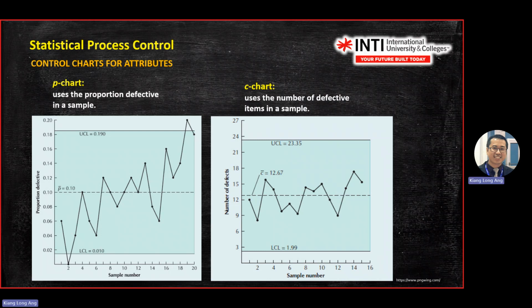After you find the mean, upper limit, lower limit. LCL is the lower control limit. UCL is the upper control limit. There's a formula for LCL and UCL. The formula will be A plus minus Z sigma. It always looks like that, but it depends on what graph you want to plot: A plus minus Z times sigma. So it depends on the question. The Z is the one that you'll see in the question. If they say the sample is 99.something percent, Z is 3, because this is 6 sigma: 3 on the left, 3 on the right. 95% will be 2. 60-something percent will be 1. So the Z number comes automatically from the question.